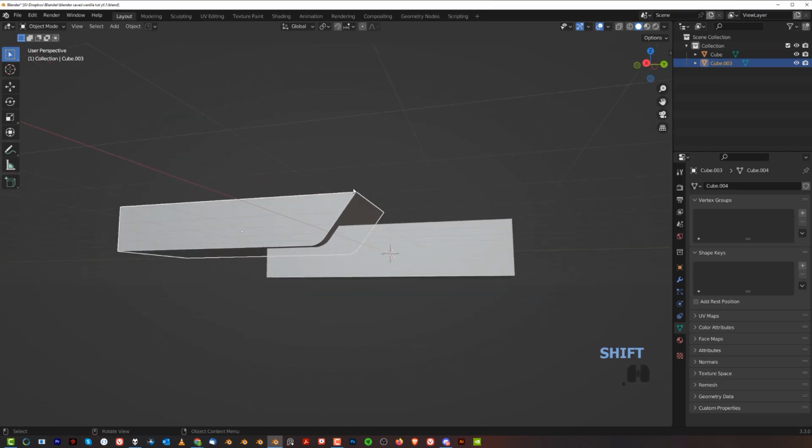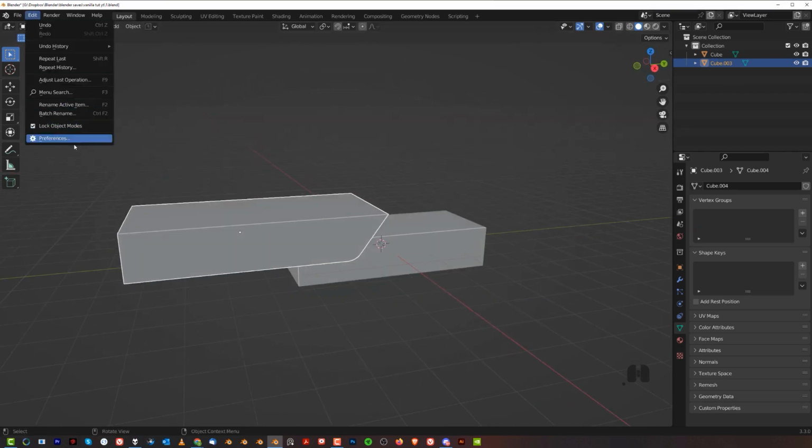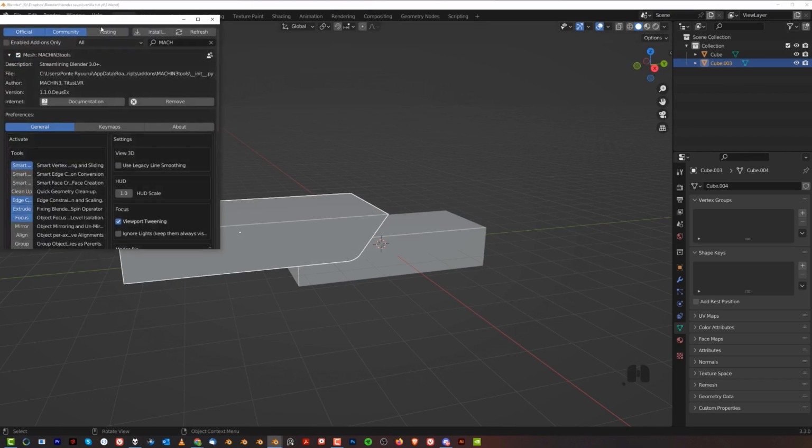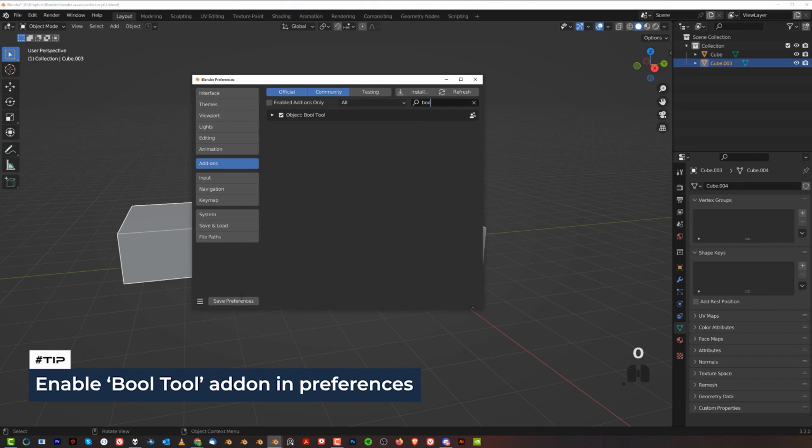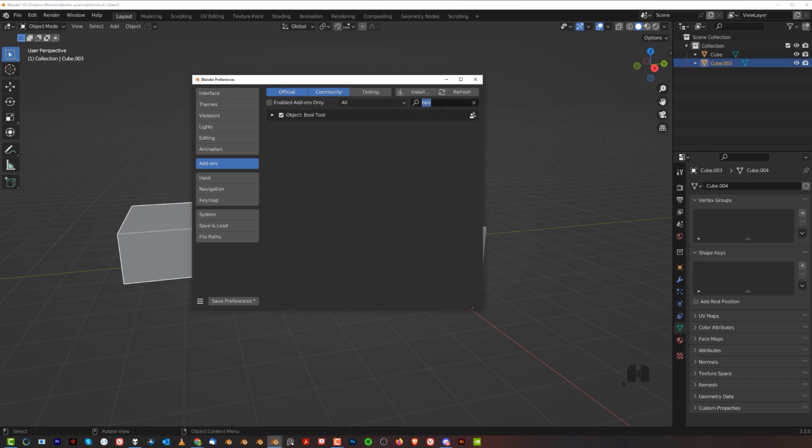So like I said, here's edit mode, object mode. Very convenient. Now we're gonna add another add-on here. It's a Blender native add-on called Bool Tool, and I want you to type here Bool Tool. Click on that and save preferences. If you don't see save preferences, simply disable auto saving, right? I like to have control over what I'm saving in terms of preferences. You may also enable Loop Tools. We may be using this, so enable that, save prefs and you're good to go.